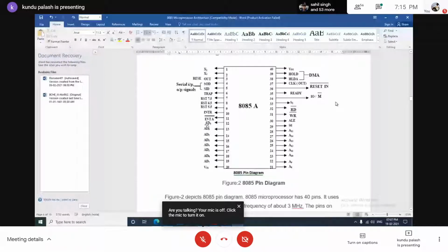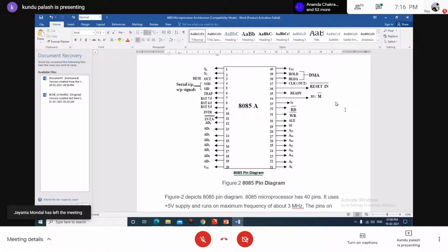In fact, whenever the 8085 addresses uniquely the locations of the memory or IO, input output devices, that means a typical microprocessor must be interfaced to form a microcomputer with some amount of semiconductor memory, different types of memory, as well as the input output systems called the IOs. So as a minimum subsystem, at least some amount of the peripheral IOs and the semiconductor memory must be connected or interfaced properly with 8085. Then only it is possible that the 8085 will work successfully upon application of the power supply,